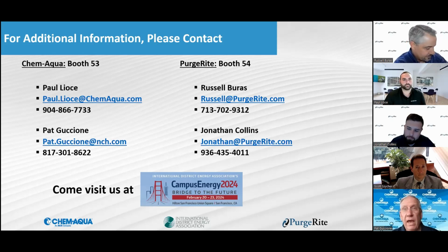HDPE doesn't have some of the inherent problems that carbon steel or other ferrous metallurgies have, but there's always enough metal in the system, valves, chillers, condensers, all sorts of things, that it's also a good idea under best practice to do a passivation, so that you protect the metallurgy in the system, even though the passivation isn't going to do a great deal for the HDPE. And just incidentally, we're great fans of using HDPE in any sort of underground piping situation.